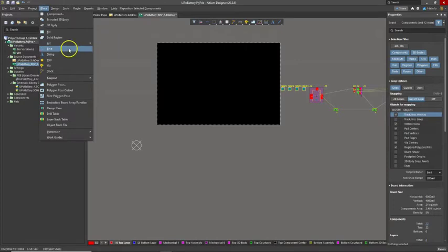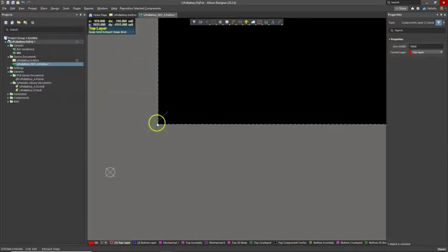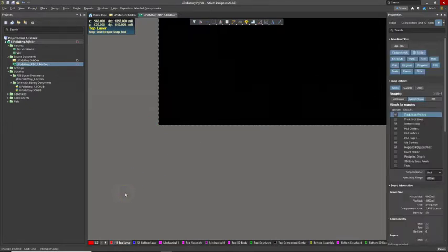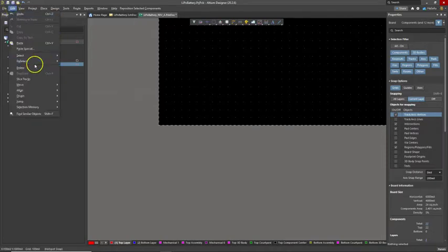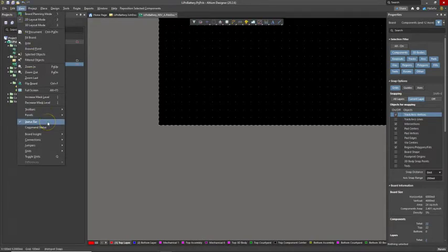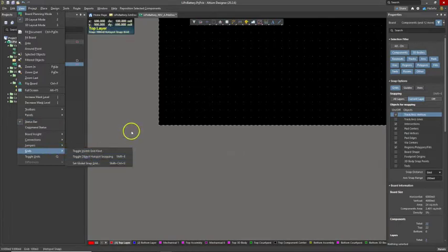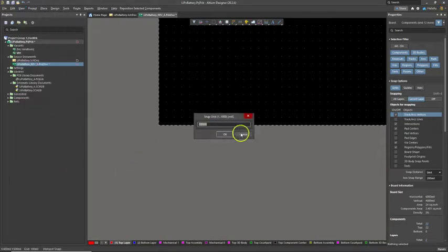You can also do place line. It's up to you. Now, I would go over here. But before I do that, there's one more thing. The grid. Let's set the grid to something large, like 100 mils for this kind of thing. I'm at 5 mils right now. So you can hit G on your keyboard and then do 100 mils instead. You can also select the view and then your grid options. So view, grids, setup snap grid, toggle visibility grid, and so on. If you set up snap grid, you can set it manually there too.